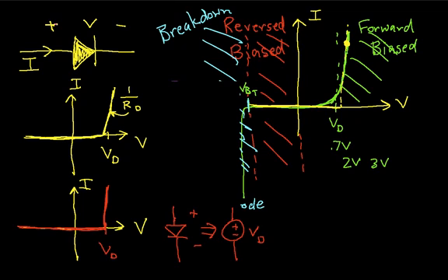When the diode is reversed biased, so basically this part of the model applies over here, then the diode just looks like an open circuit. Now this is again useful. Most of the time you'll see this used when V sub D is a significant fraction of the maximum voltages that you're going to use.